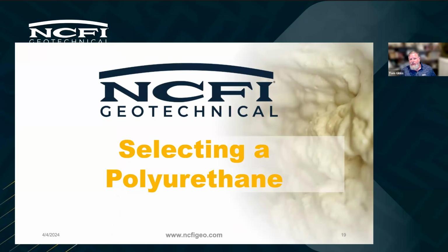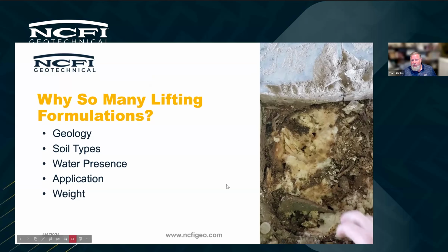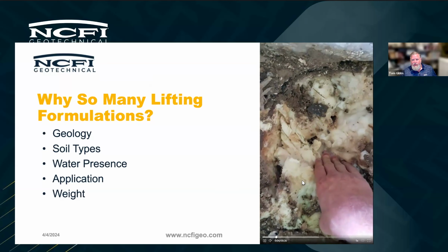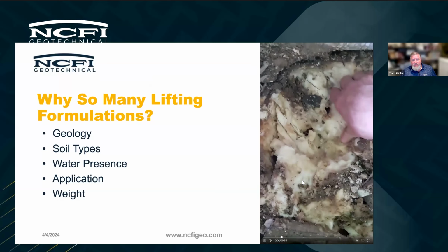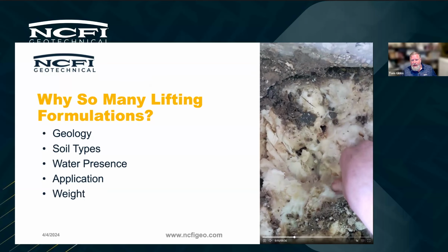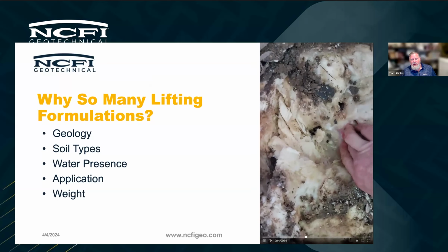Selecting the polyurethane for your project. So why do we have so many lifting formulations? I mentioned earlier, we've got over 25 different systems, and there's a reason for that. This is a good example of a foam that was not selected properly. As you can see, it absorbed quite a bit of water. We have some systems that are not considered hydrophobic or hydro-insensitive.